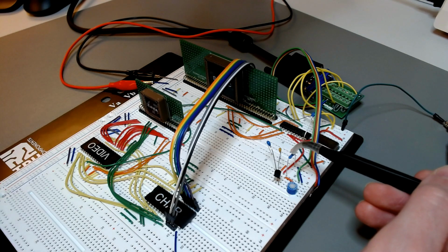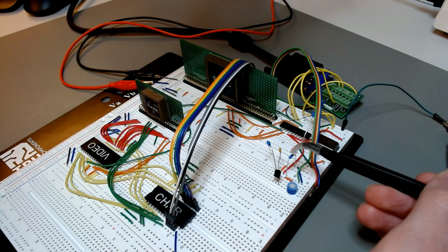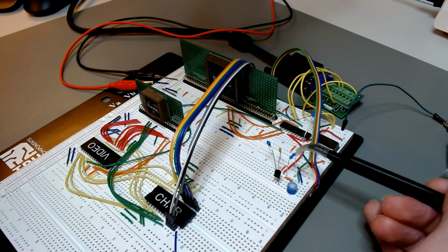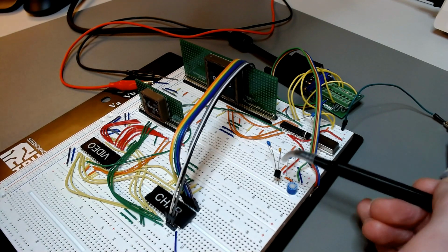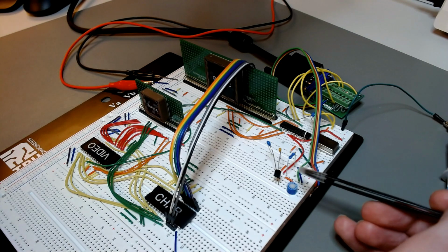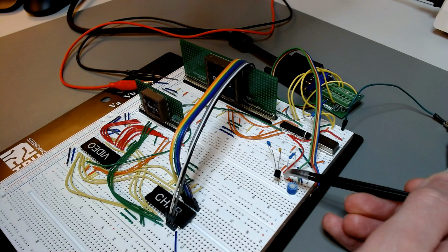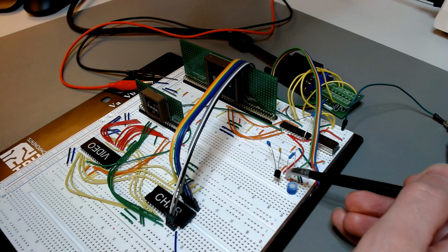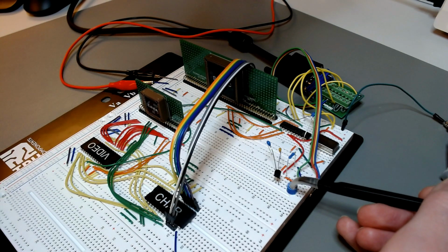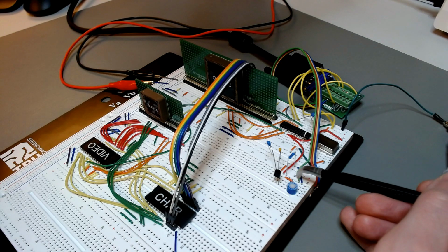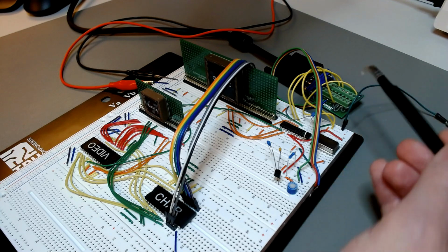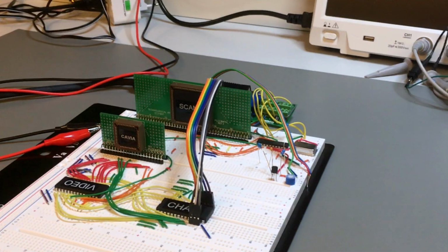I've chosen a 75 ohm resistor here in order to do some impedance matching with the monitor, which is spec'd at 75 ohm, and that reduces the rippling and makes the signal a little more stable. And then the video signal is finally collected from the emitter of this transistor on top of this resistor here, and that goes through a trim potentiometer and then into this green wire here that goes all the way to the connector, and that's the green signal.